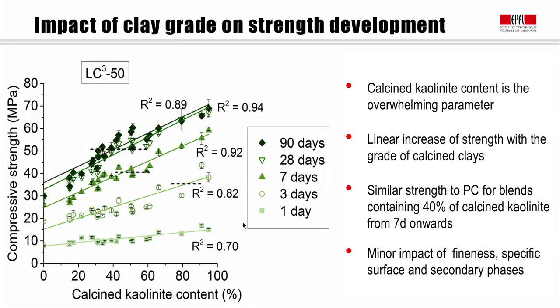And if we have this happening, we'll get a very strong decrease in reactivity. So the critical question now is, what grade of clay do we need to be able to make these LC3 materials? So at EPFL here, we've studied a wide range of clays from around the world. These clays had different origins. Some came from Latin America, some from India, other parts of Asia, etc., even from Europe. And the fineness of this clay, the production method of this clay, the minor phases that were present in addition to the clay, all of these varied quite widely between the different materials.